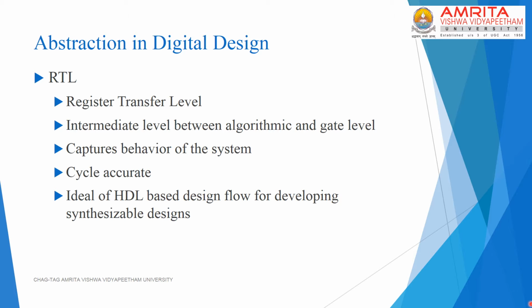So now we have the register transfer level or the RTL abstraction, which has characteristics of both the gate level and the algorithmic level. It is somewhat similar to the algorithmic level in that it is able to capture the behavior of the system. At the same time, it provides a cycle accurate description of the system, so that in that sense it is more aligned towards the gate abstraction.